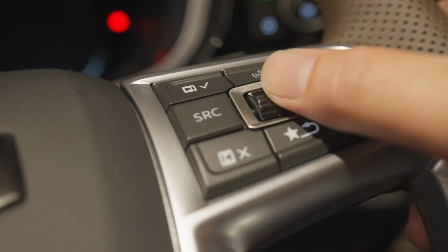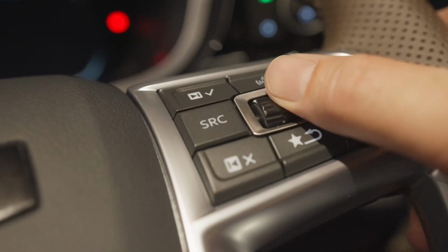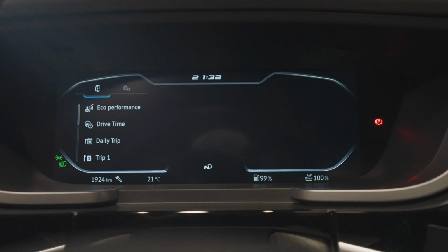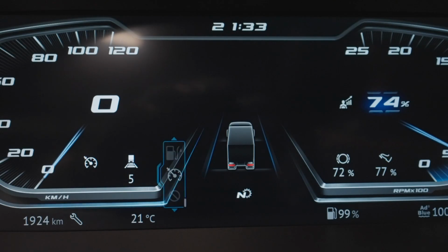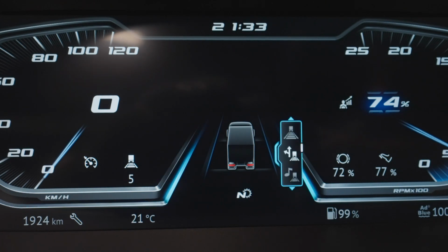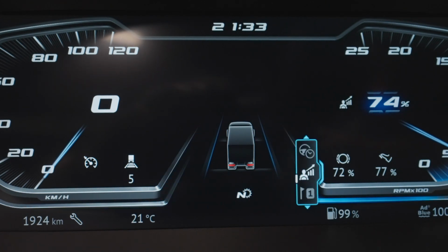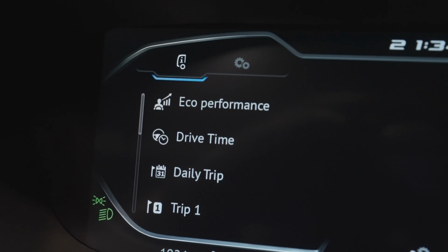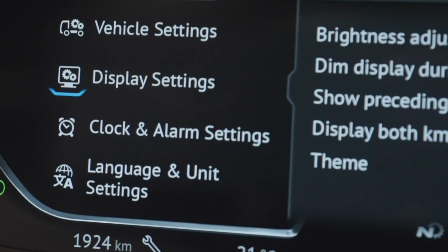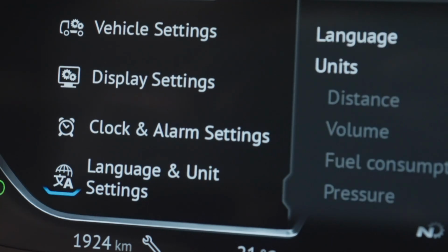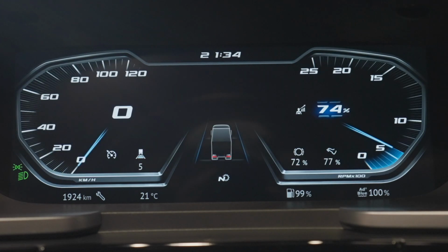Menu control is opened by rolling and pressing the right-hand side switch pod centre wheel. There is a back button underneath the scroll wheel. This is also used to access your favourites, designated with the star. 2 main menus exist, one for the vehicle information and one for settings. The blue highlighted part of the menu is the active segment. Holding down the back button for 2 seconds will return to the home screen.